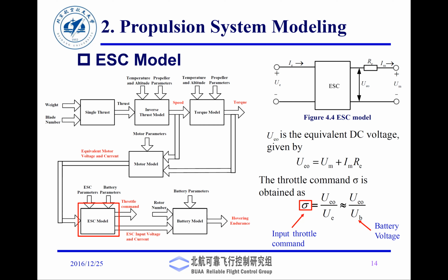And that is how you can approximate it. Just to give you a simple example, if you look at the brush DC motor, if you apply 1 volt to the brush DC motor, it will rotate slowly. If you apply 12 volts to the brush DC motor, it will rotate fast. So fully rated voltage versus a partial fraction of the voltage will dictate how slowly or quickly that motor rotates. So you can think about it like a throttle.